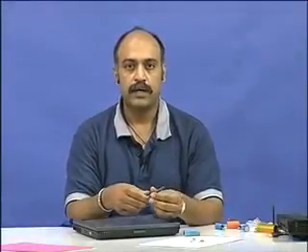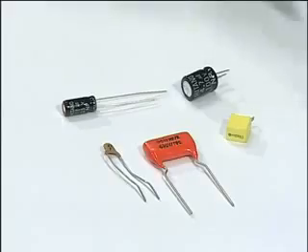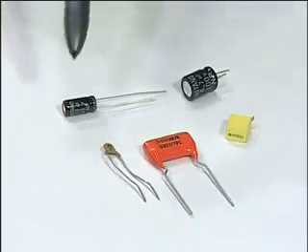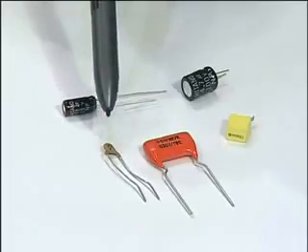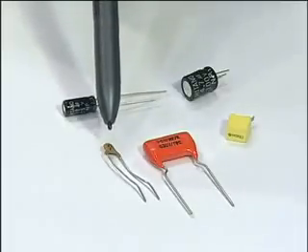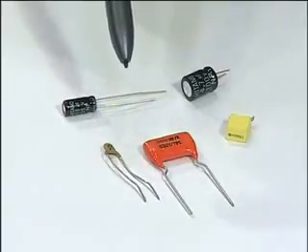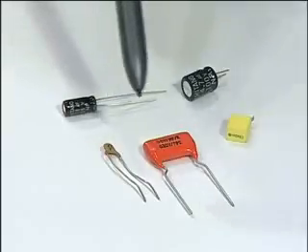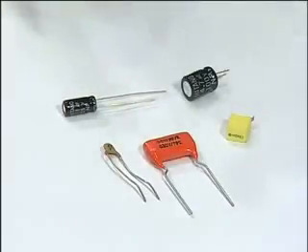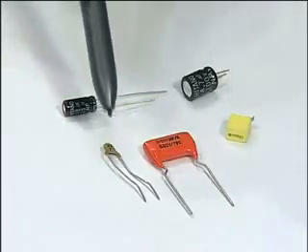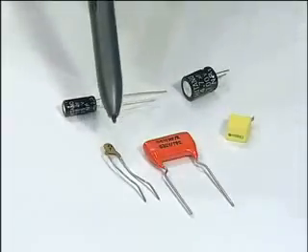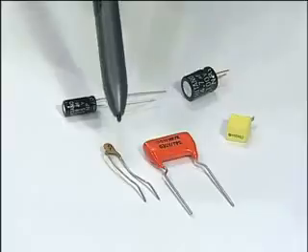Let us now look at some of the capacitors that you will find in the real world. If you look here spread out, there are a few capacitors. The smallest one here is a paper capacitor, and as I told you earlier, in the case of resistors you have the color codes for the values, but for the capacitors the values are printed on the body of the capacitor itself. So, you need not remember any color coding for this. This is normally used for decoupling in electronic circuits.